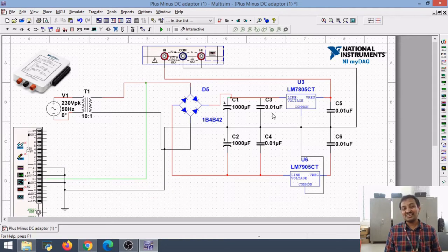Even if the load current changes, the output voltage will change. The load current can change due to different factors, like a voltage drop at the transformer winding, at the rectifier stage, or across the filter stage. Due to these limitations, it is impossible to get a constant voltage. That's why, to avoid these limitations, we have taken another block, which is a voltage regulator.